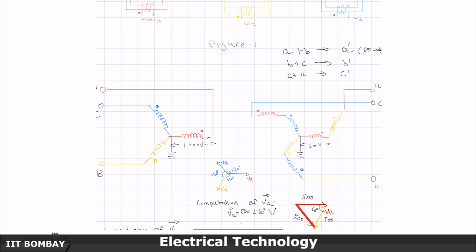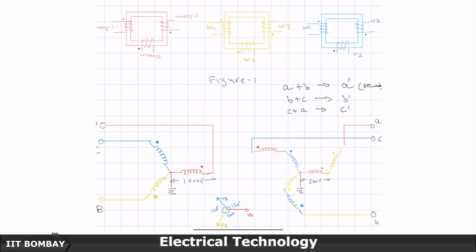So, if you look at it from outside, it is just like a 2 winding 3 phase transformer, but it is built out of 3 single phase 3 winding transformers. So, that's the interesting part. That means these windings here in some sense get interconnected, as I have shown here, to bring out only one output terminal later on.